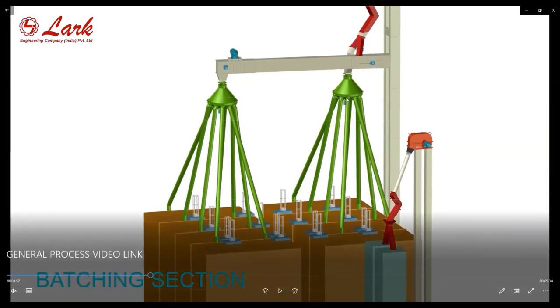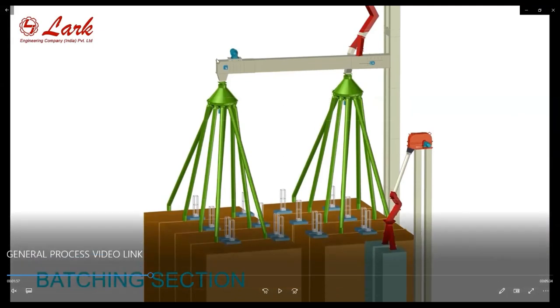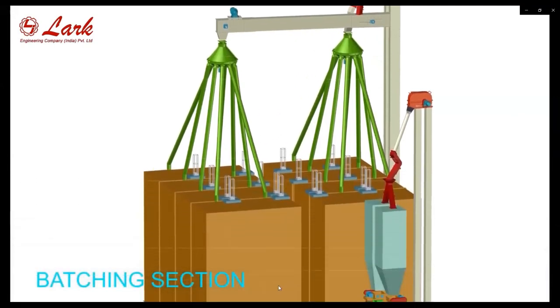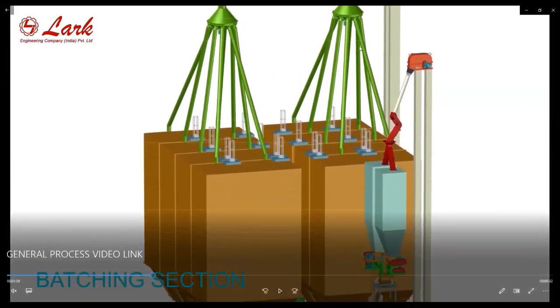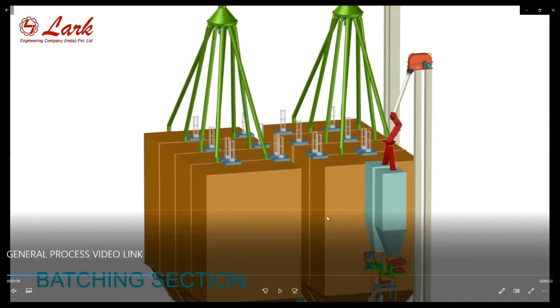You can see the angle of this distributor is even more than 70 degrees, 65 degrees, so that there is free flowing of the material and very little jamming. Even with fibrous material like cattle feed and other fibrous material, we have to check the angle of the chutes and the ducts. And even this rotary distributor only works with a 1 HP motor. Only a 1 HP motor guides the material to all dosing bins.